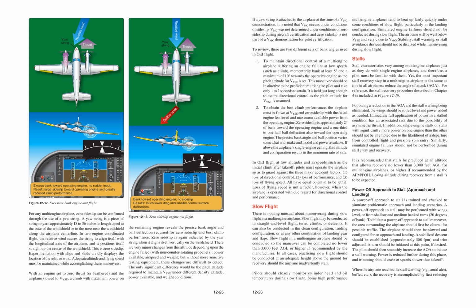Excess bank toward operating engine, no rudder input. Result, large side slip toward operating engine and greatly reduced climb performance.